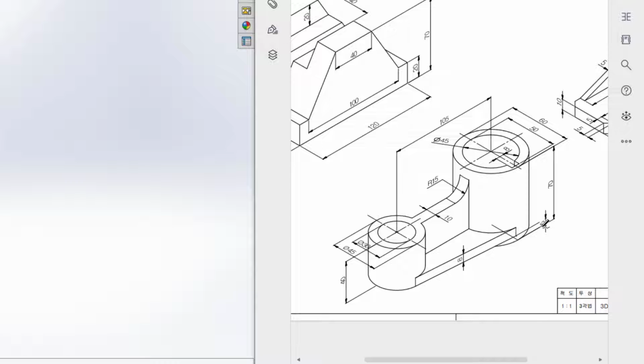Okay, then from the right plane I will draw a line here and another vertical line here. Then I will use the fillet to fillet it to radius 15 unit. Then I will close the shape, and before closing the shape I'll extend this line to this side and extend this line to this side, because as this is a round shape, this portion will be a gap. So I'll extend this portion a little more. Then I will close the shape like this.